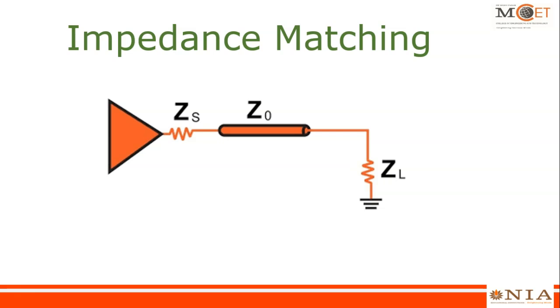In high frequencies, whenever the signal passes through these transmission line components or a resistor, the signal will be time delayed, and for an AC signal, a phase shift will occur. It means the complex reactive part dominates, more than resistance. We have to nullify that reactance part, right? Impedance is a complex quantity, whereas resistance R is a real number. Impedance is R plus jX, right? So here we have to remove the reactive component first. We have to eliminate that jXL.